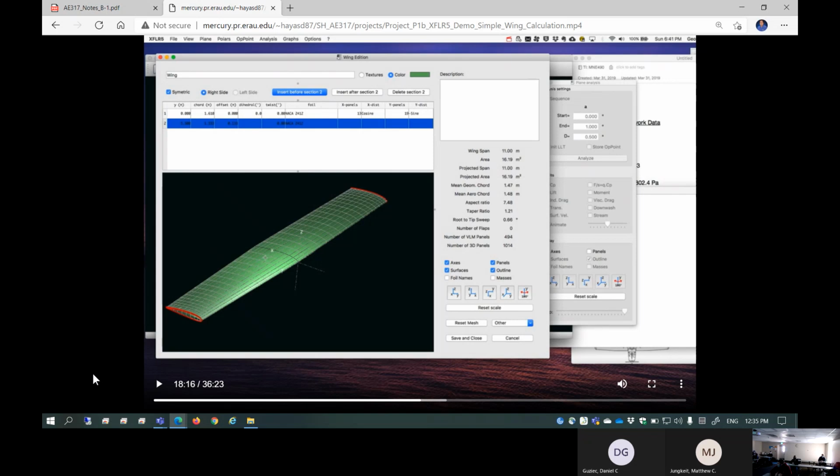3D panel, right? Yeah, we used to. Did you use VLM? Are you sure? I thought you used 3D panel. 3D panel is a standard nowadays. This guy's using VLM. You can use it, of course, but I would recommend the 3D panel method, which is almost close to a computational fluid dynamics type of panel method approach in 3D space.